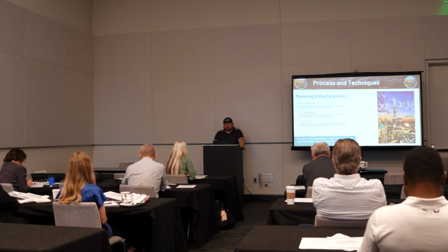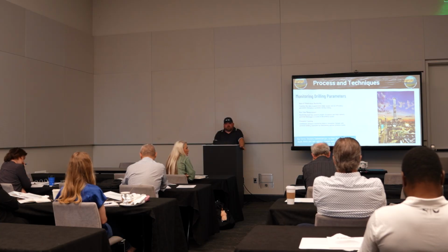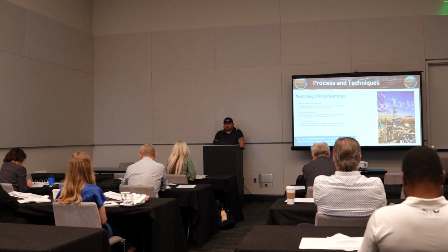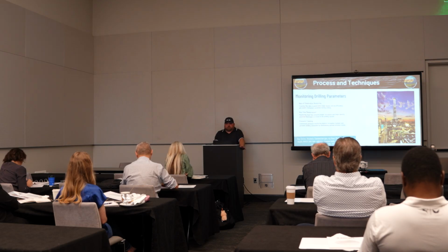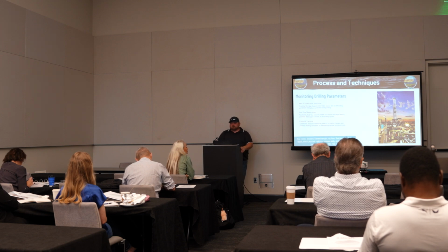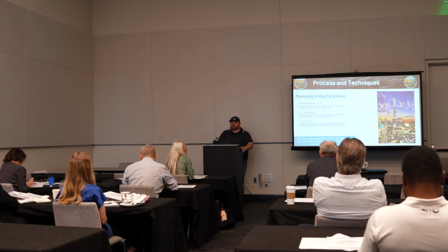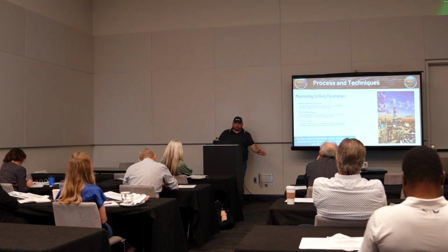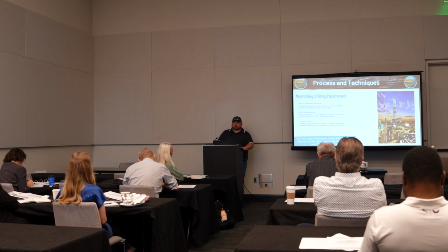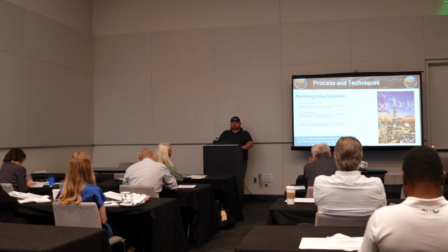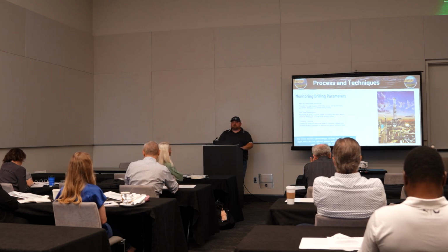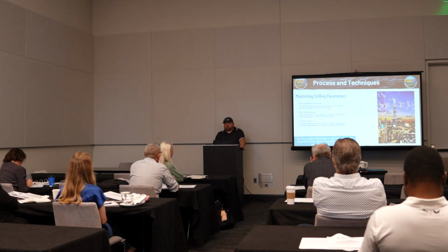Mud motors go bad. It's a mechanical piece of equipment that directional drillers use to steer the well, and they do go bad. Anything mechanical can and will break. So when they go bad, usually you'll get a pressure spike. It has nothing to do with the formation, but it's still something you need to confirm and look at from a safety standpoint alone, let alone talking with your geology department, drilling engineers, and all that. So that's another thing to put on the mud log.